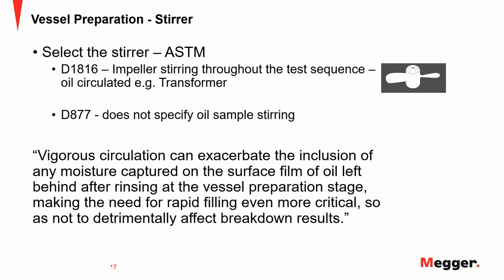So you're actually stirring the actual oil, but you could also potentially, if the sides of the vessel have been contaminated with the previous sample because of the oil being adsorbed onto the surface, which may then contain moisture, you're then stirring all of that into your specimen sample, which will then affect your breakdown results. So this is why it's key that once we've rinsed the vessel, we then make sure that we fill it immediately afterwards in order to avoid that.